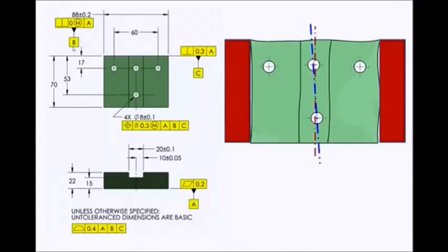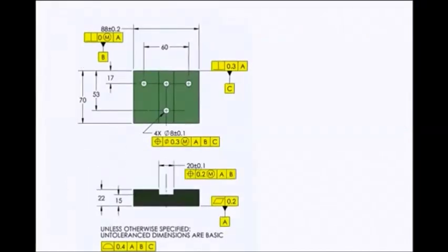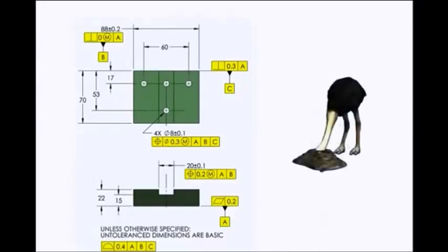And some people say, well, that's the datum feature. Yeah, but this doesn't reference the datum feature. And I don't know what the precedence is. Is B supposed to be used as primary or secondary? This drawing doesn't tell you. So please don't use those half dimensions, especially on these tolerance dimensions like the 20. Do it the right way and control its location using position. And stop burying your head in the sand with those old methods.